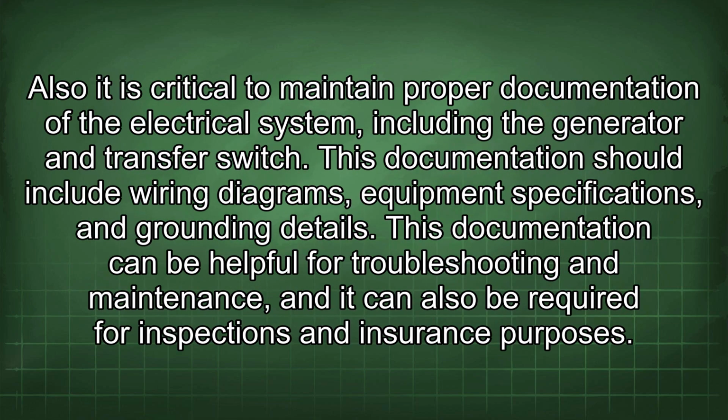Also, it is critical to maintain proper documentation of the electrical system, including the generator and transfer switch. This documentation should include wiring diagrams, equipment specifications, and grounding details. This documentation can be helpful for troubleshooting and maintenance, and it can also be required for inspections and insurance purposes.